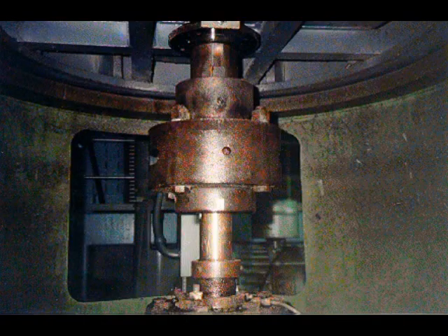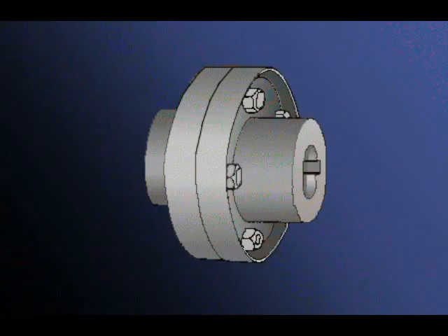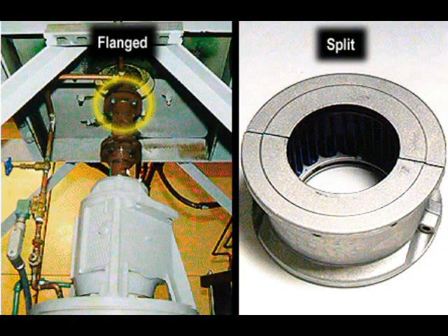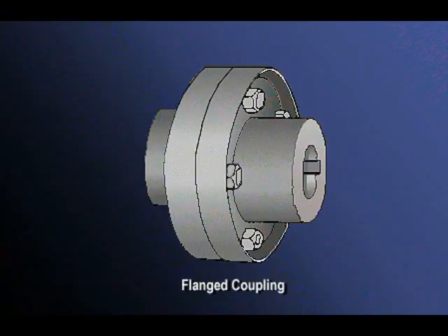There are 3 commonly used types of couplings: rigid, flexible, and V-belts. This source will consider the rigid coupling first. Rigid couplings are most often used on vertically mounted pumps. The rigid coupling is usually specially keyed or constructed for joining the coupling to the motor shaft and the pump shaft. There are 2 types of rigid couplings: flanged and split. The flange coupling is used when the motor shaft and the pump shaft to be connected are different sizes.